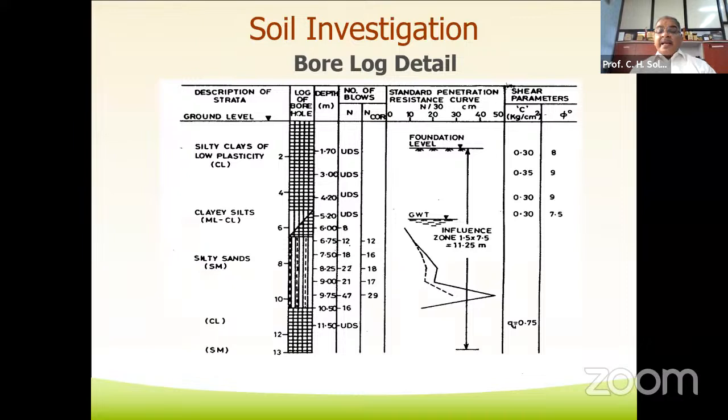This is the borehole detail given in the data. In this borehole, the type of soil at the different depths has been given. Where the UDS sample has been taken has been presented. Where the SPT test has been conducted and what the values are has also been presented. The foundation level is also presented.